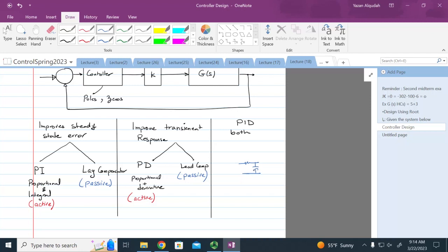That circuit that we designed, this part, does not. I can connect it to a power source, but the power source is used as input, not to power the circuit. Versus an active circuit where you have an op amp, you still have this input, but this one has to have a power source. Make sense? Thanks for asking. Good question. We will see both of them, and hopefully that will become more clear.